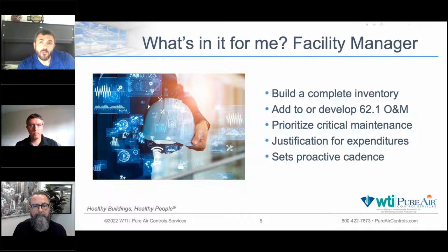Another example would be, we've seen a situation where you have internal insulation inside of an air handler, and it starts to come away from the internal walls of the air handler, and then eventually reaches a point where it totally comes off the wall or comes off the floor, and then is blocking the coil because the air is flowing through the coil, and it becomes actually an obstruction of airflow through the coil. And so that's something that we come across quite a bit in these single wall air handlers that have this internal insulation that's just come off after years and years of deterioration.